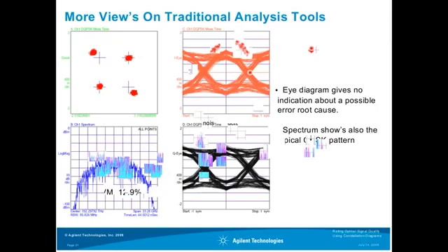But if we look at the error vector magnitude in this diagram, we can see some dominant structures like a kind of V-shapes. In both cases, we see an increased error vector magnitude of close to 35 and 33%.